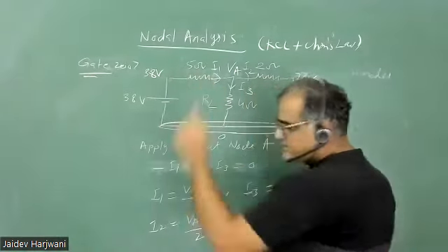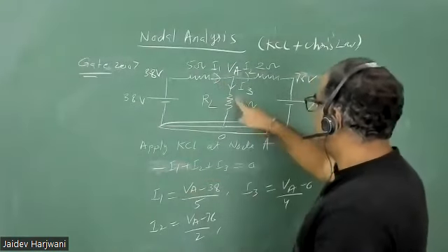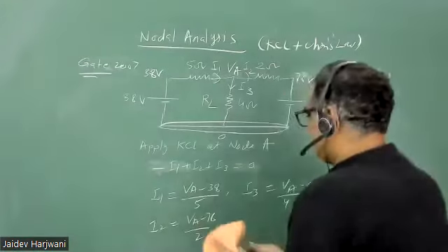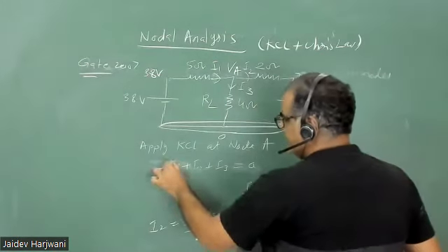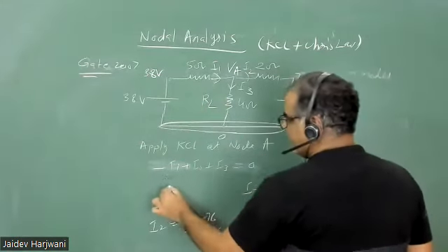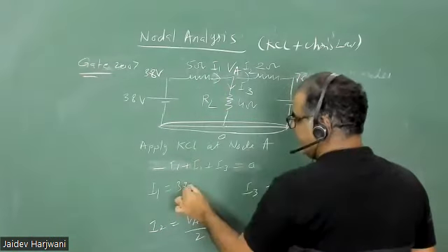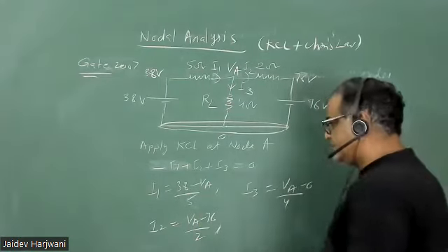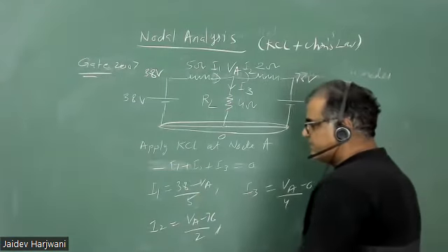Okay. Let us put like this. What is the issue? Okay. So this is incoming current, I'm taking negative, and outgoing current positive. Now I have to change the expression for I1 if you want. So now my I1 will be, because it's moving like this, I1 equals 38 minus VA upon 5. Okay. So now put the values and calculate, and tell me what answer is coming.